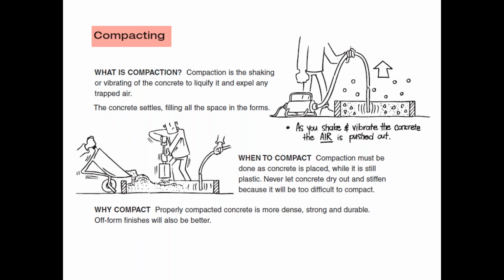And the off-form finishes, that's the formwork that holds it all in place when you're doing it, will be much better as well. All right? So we're trying to get rid of any trapped air.